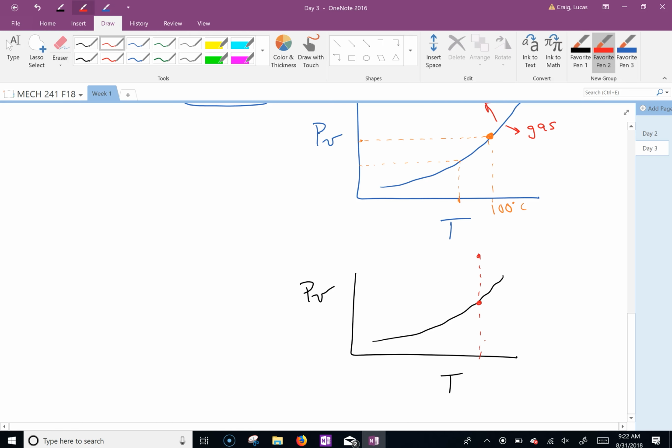So if the liquid is at higher pressure and there's low pressure, which way is it going to go? Inflow. Yeah, it's going to go in. We haven't really talked too much about pressure, but hopefully you have an idea. So when you hit the gas and the prop spins, it drops the pressure in certain areas, the liquid forms air bubbles, and then they implode because they're at lower pressures. It's the little implosions, and that's what happens. You get issues with the prop.